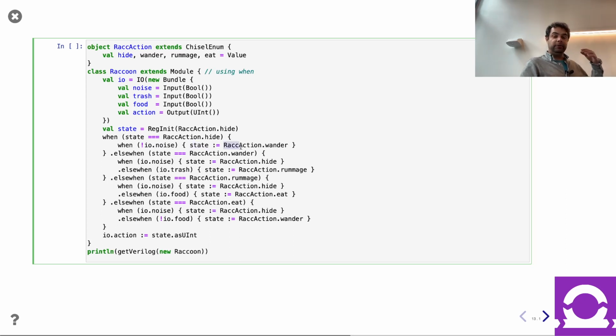I've connected it to this particular literal, in this case, enumerated value. And so I connected the input to that. And so then when the clock cycle terminates, the next clock cycle starts and takes that value. So this is a very direct way of writing it. You don't have to keep having state, next state, etc. It's just all state. And remember, state is a register in this case. And we're just comparing the output with these when statements, and then we're changing what the input is connected to over here. And we'll see when we write the Verilog in a second. But yeah, all these combinations of whens and these changes of state, there's a bunch of muxes, right? That's going to happen. But that's the key thing.